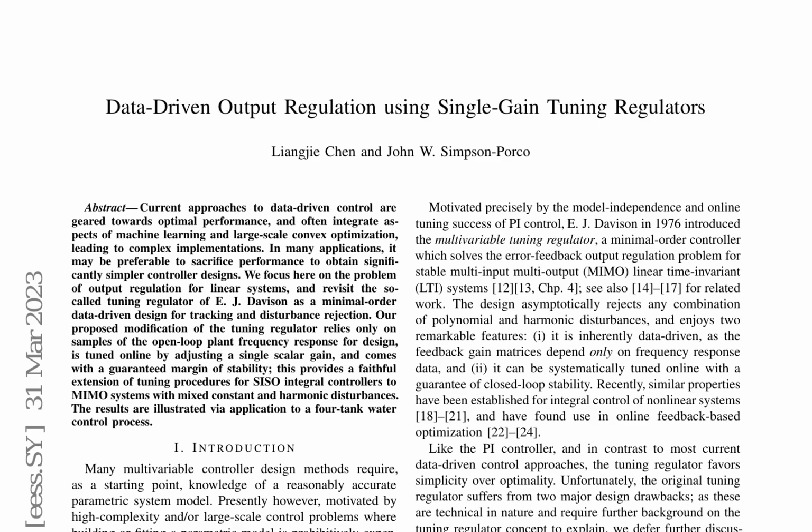In terms of stability analysis, the closed-loop system with the SGTR is evaluated for low-gain Hurwitz stability. This requires the dominant eigenvalue of the closed-loop matrix A to be ε away from the imaginary axis for sufficiently small values of ε. A pivotal result in this context is the development of the steady-state loop gain, SSLG, operator L, which plays a key role in characterizing the low-gain Hurwitz stability of the closed-loop system.